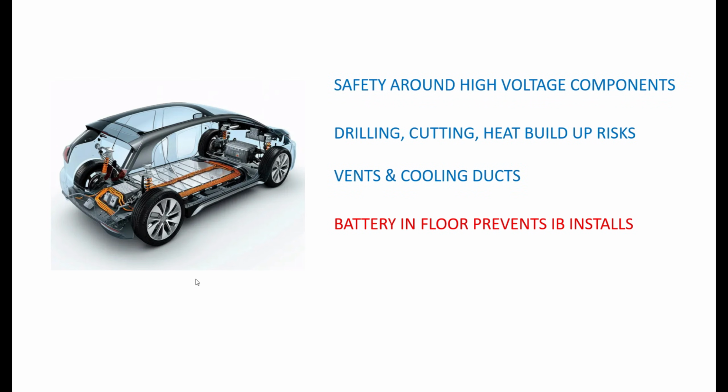The other thing you need to be careful of is where the batteries are. For example, in an EV, if the batteries are in the floor, then clearly you're not going to be able to put in IB installs. You're not going to be able to cut holes in the floor and put your mid-bass under the seats with the back wave venting out to atmosphere, because there are batteries and wiring in the way, right?